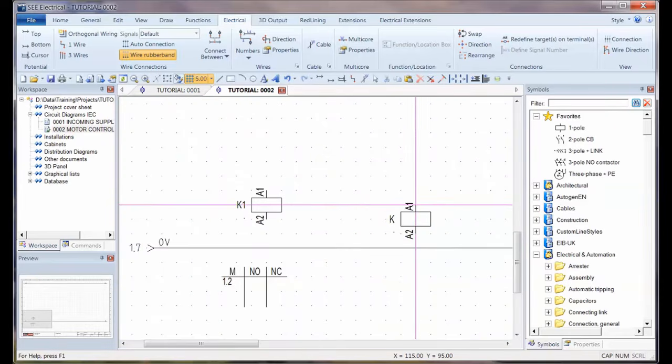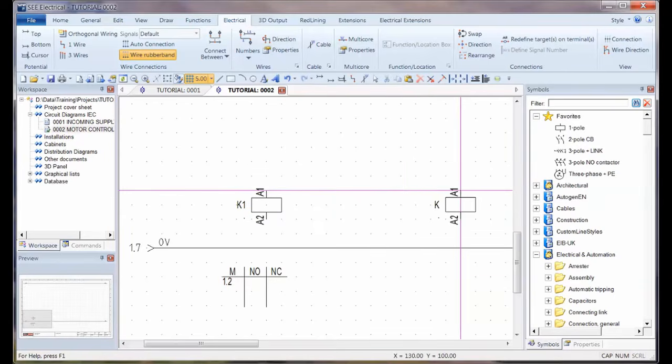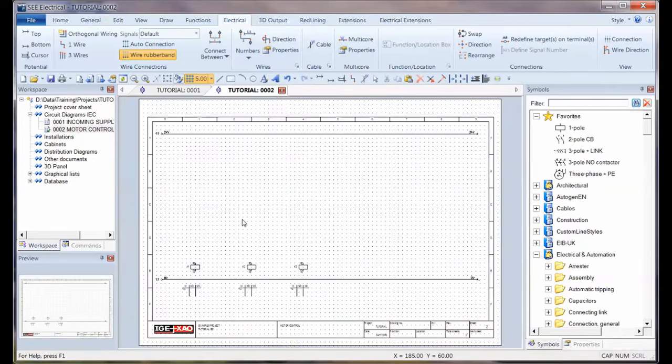It's called a K, and it's given the first number, so it's referenced already what's on page 1 column 2. I'll do the same thing with the next line, K2, and again for K3. So that's fairly straightforward. Going to zoom out, so that's holding down control, wheel backwards, single wire. I'm going to go all the way from the bottom through that symbol, and it's just going to connect. On these two I'm going to switch between these, so I'm actually just going to go up like that, and have another one which goes across and down. So I've got a gap of 10 millimeters, 5 millimeters there.